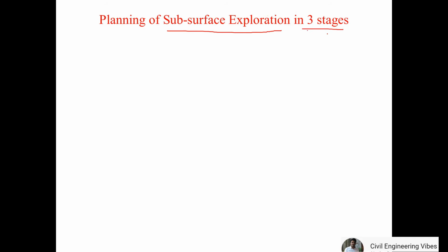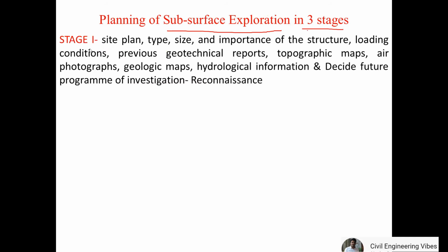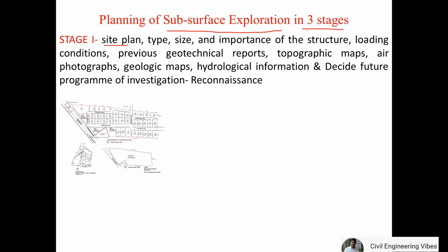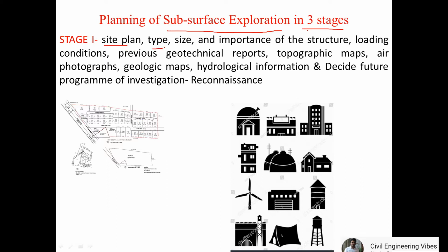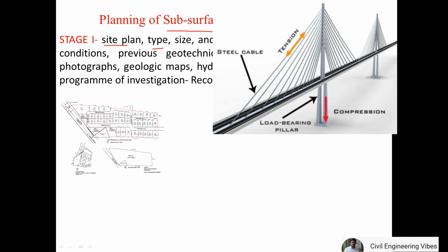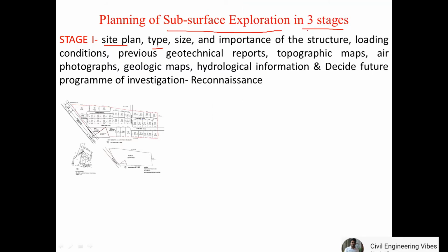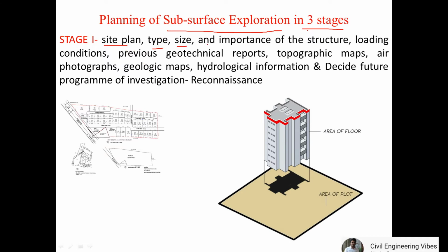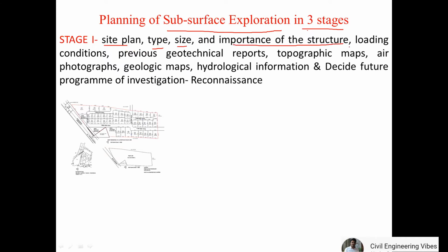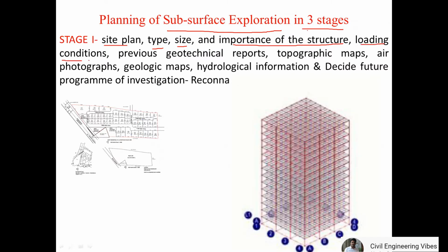Stage 1. In general, investigation should start with the collection of the data: the site plan, to get to know where to investigate, the boundary conditions of the investigating site, and the type of the structure, whether it is a surface structure, solid mass, framed, truss, cable and arches, etc. Size signifies the coverage area of the structure. Importance of the structure, whether it is a major or a minor structure. The loading condition. Probable structural load is to be known.